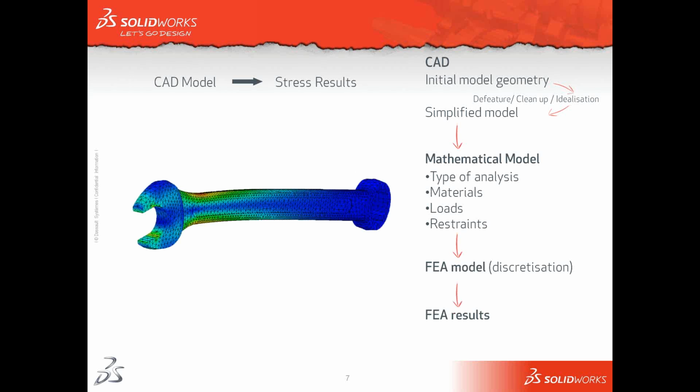results. There's a lot of tools available in SolidWorks that allow us to analyze the results in great depth, and we can get a lot of really handy information out of there, which is really, really useful, because if we were, say, conducting a physical test, you don't really get too much information. Maybe you'll see a failure, you'll see something that's broken, and you can see where it's broken. Whereas with the simulation tools that we've got available here, we can see why it's broken. We can see how stresses were propagating throughout the model. We can see where stresses may also be reaching high values, but we didn't see a failure in the physical test. That's what's really, really handy here.